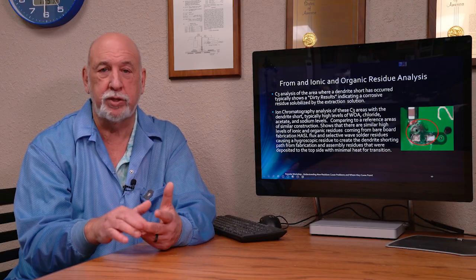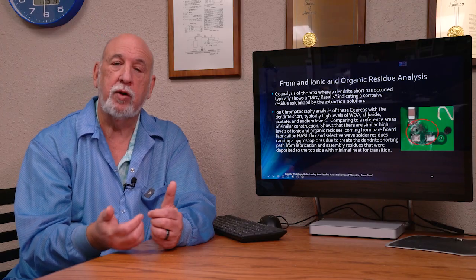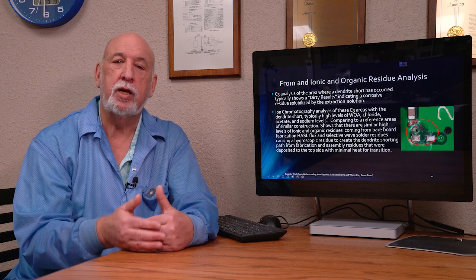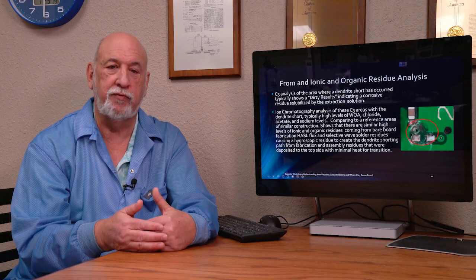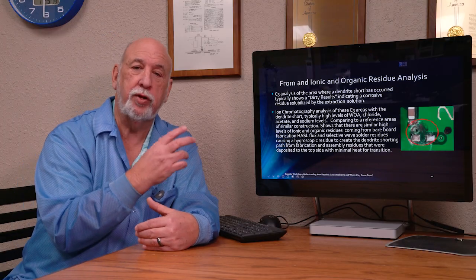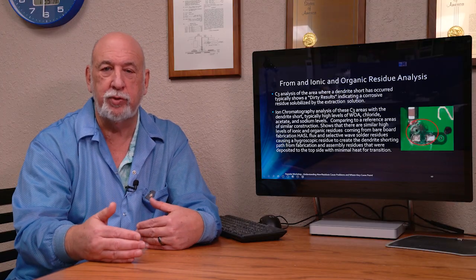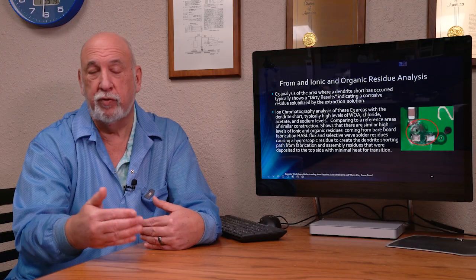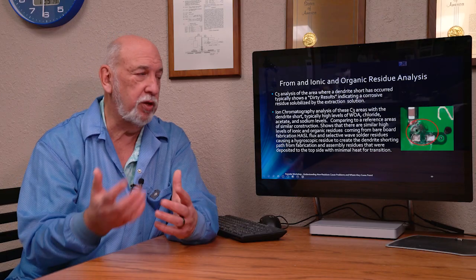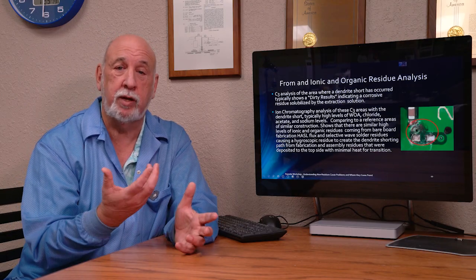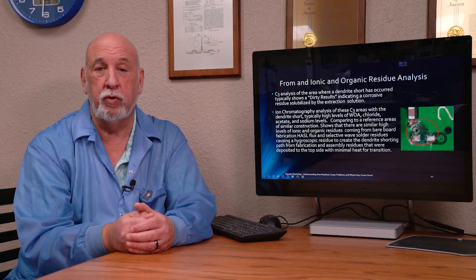So adipic, butyric, succinic, all of these common acids used in the no-clean fluxes require additional thermal energy and need to be properly heat activated. And so we've been counseling a lot of fabricators and assemblers to make sure that after their selective soldering process, boards see additional heat to hold a temperature of between 125 and 150 for 30 to 60 seconds, depending on the volume of material that's there and the amount of thermal mass. So we have to look at those variables. But if that flux gets to the top side and is not properly heat activated, it sets up a beautiful opportunity for dendritic growth and corrosion.